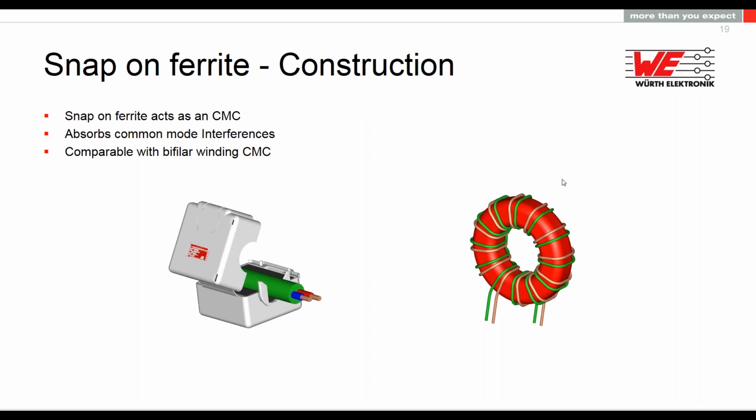Most of our cores, when we coat them red, are made in manganese zinc. When we coat them green, most of them are nickel zinc. When we coat them black, they are nanocrystalline. When we coat them yellow, they are iron cores. When we have yellow and red painting, it's also iron cores. So you have to pay attention, or ask the product manager or the sales guy which kind of material has been used, and if this is right for your application. And if you have just 2-3 turns, the nickel zinc common mode choke will be maybe 10, 15, maximum 20 microhenry and never ever millihenry.